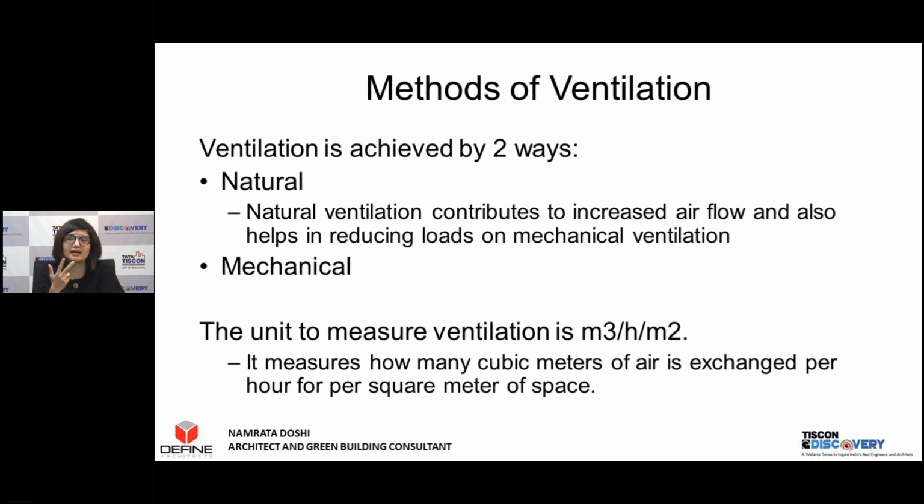How does this impact design or engineers? So let's say you have a room of 15 square meters, that's 150 square feet approximately. It is important for you to understand how many cubic meters of air you need to exchange in a particular hour per square meter of that room, multiplying it by 15 to give you the actual total volume.